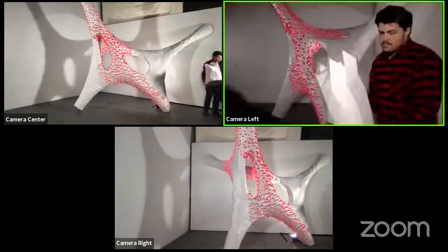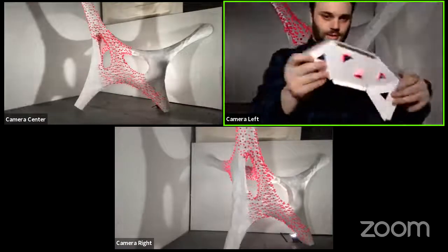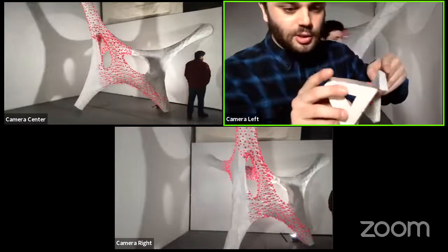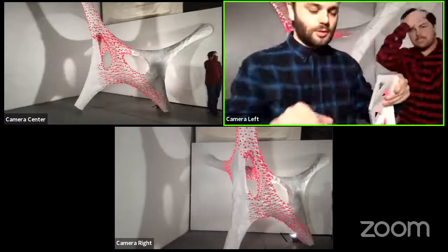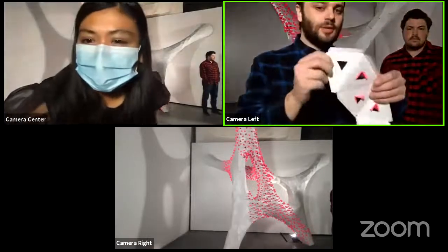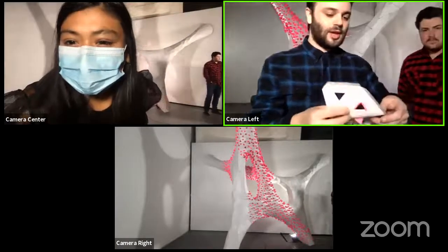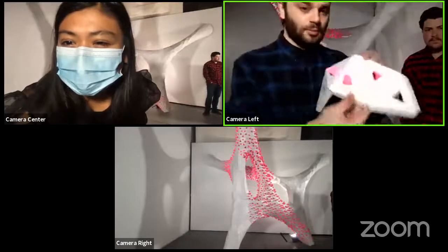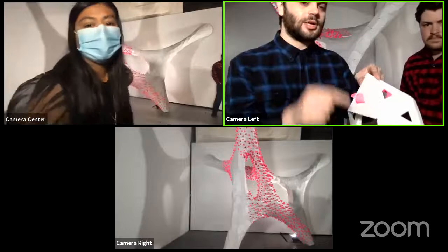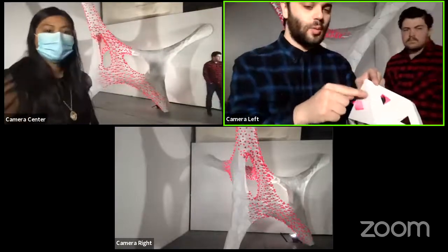And here's an example of an extra strip we had, or one from the prototyping. And you can see that each edge is perforated. We did that because scoring, where you don't cut through the material all the way, is only a one-directional folding technique. And some of these fold out, although most of them fold in. We didn't have any guarantee of which did what, so we went with the perforation. It's also easier because then you don't have to have a separate setting for the laser to cut halfway through the material. You can just have one setting for a full cut.